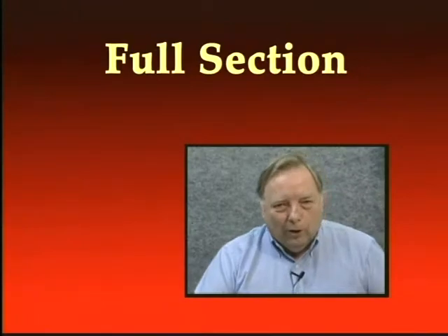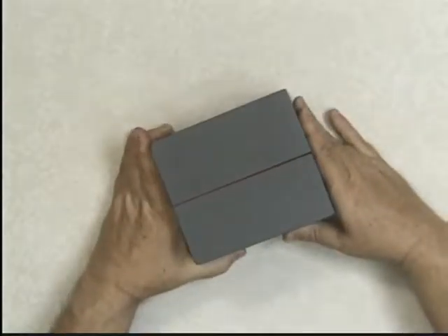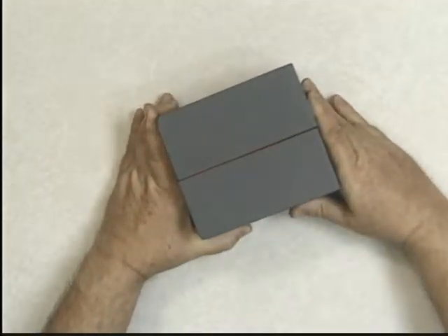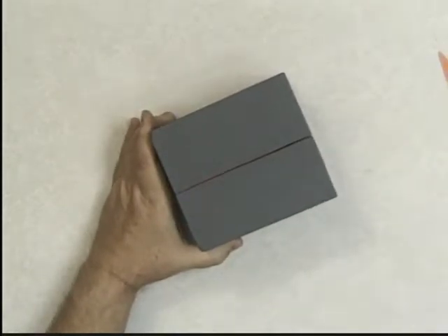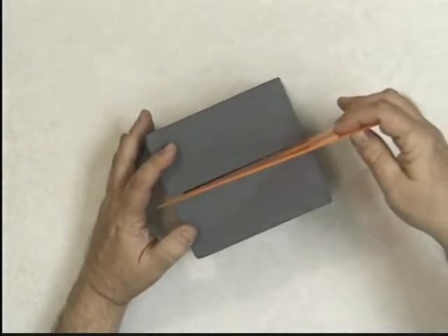Well, that's probably enough silliness with a fruit, but you get an idea of the different kinds of sections. Now let's get a step closer to reality here. Suppose I have an object like this and I don't know what's inside of it. If I drew this object, I'd have all kinds of hidden lines. So what I might want to do is do a full section. Let me take this triangle and simulate my Ginzu carving knife here.